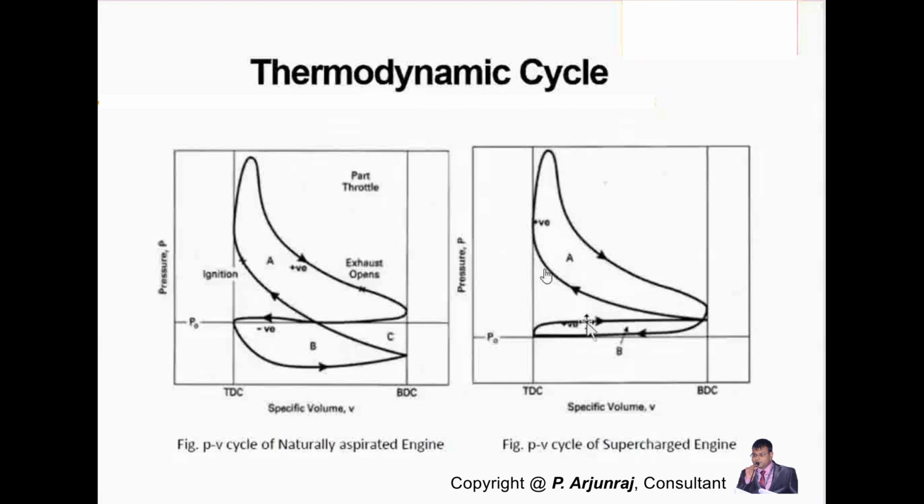Not only this, the pressure you are going to get during combustion is also going to be higher compared to that of the naturally aspirated engine. This will help you to have more fuel injected or ignited, according to the cycle or the fuel you are going to use, and accordingly the pressure increases at each and every stage.